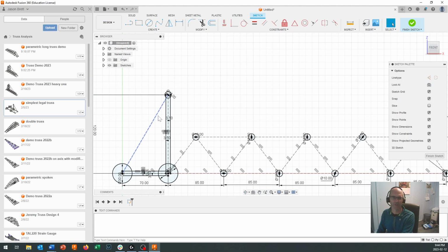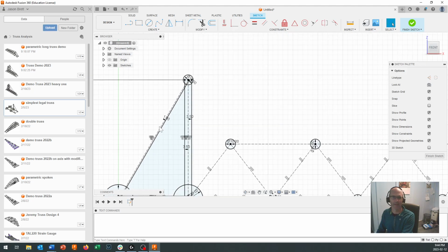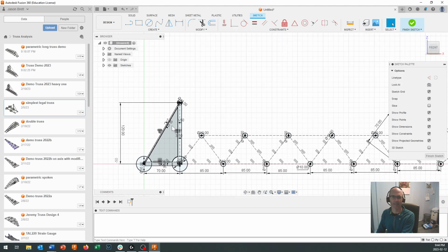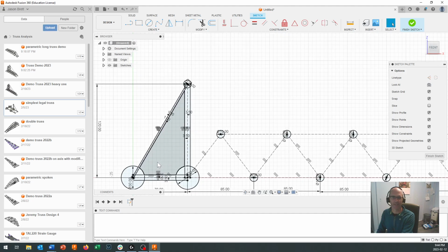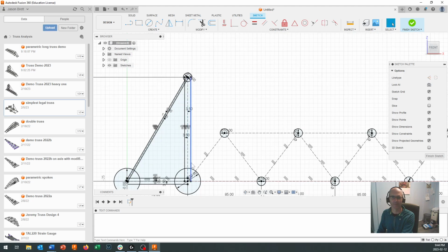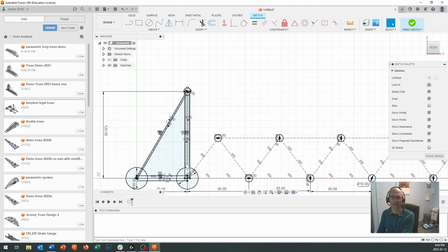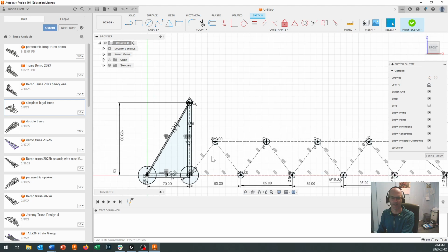Now this one should be in tension, and I do want to put a string up and down there, but maybe just to help me get that into tension, I'm going to put a little member right in there to deal with some of the tension. So O for offset, 1 millimeter on that side, and O for offset, minus 1 millimeter on that side. When I do these things, you'll see that structures start to turn black and enclosed areas start to form up. These are the enclosed areas that I'm going to be able to extrude later on.